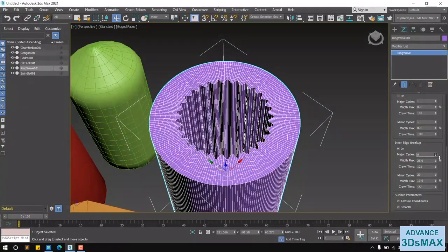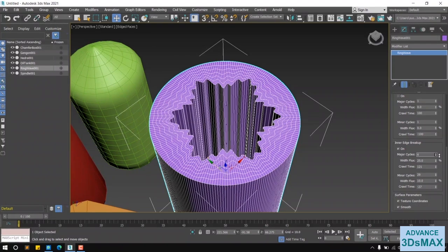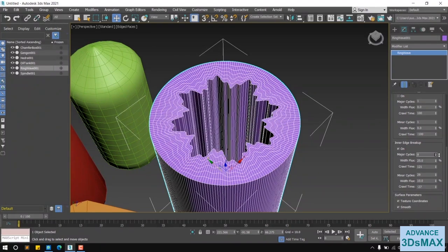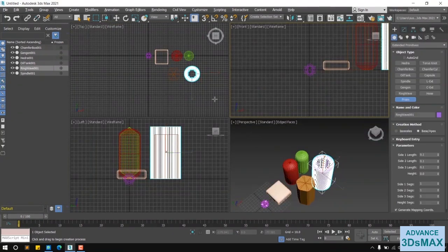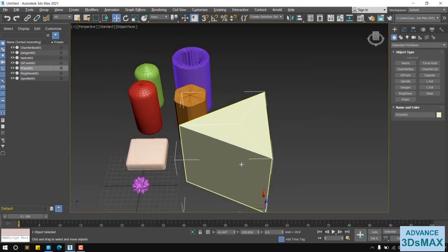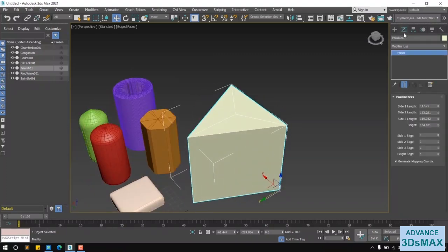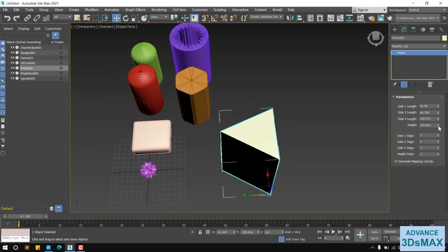Okay. So you can also modify the shape like this by changing the circles. Next tool is prism. First create one side, then provide the pointer sharpness like this, and then provide height. So it's a triangle type shape, and go to the modify section and change length 1, length 2, and length 3. Okay, and change the height.